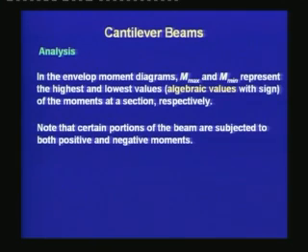Note that certain portions of the beam are subjected to both positive and negative moments. This is an important aspect of a cantilever beam with a backspan, that there are locations in the backspan which are subjected to a positive or a negative moment under the service loads.